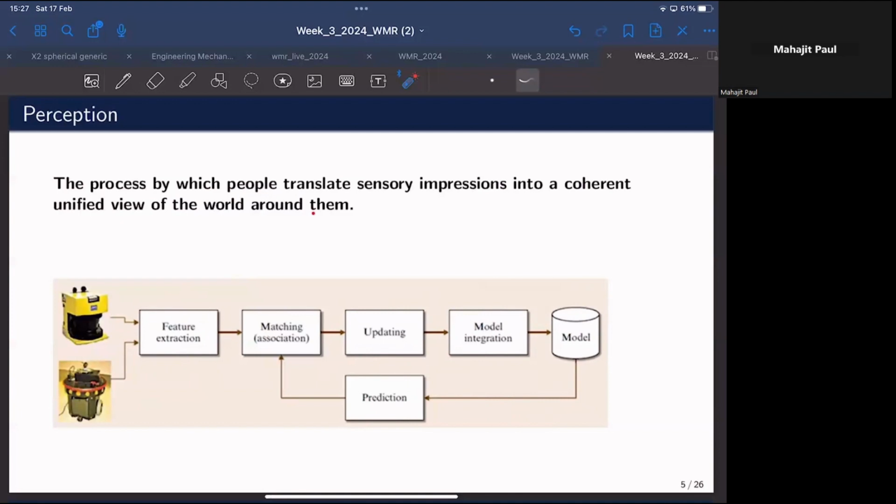If the performance of the mobile robot is satisfactory, it will update its next course of action, how to proceed forward. Whether to correct its trajectory or update its position for the next instant, it will do this via this step. Once updated, it gives the next set of features the robot is supposed to see, matches them with what it is currently seeing, and basically runs in a loop.